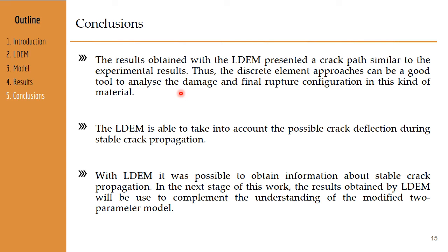Thus, a discrete element approach can be a good tool to analyze the damage and the rupture configuration in this kind of material. The LDEM is able to take into account the possible crack deflection during the stable crack propagation, and with the LDEM it was possible to obtain information about the stable crack propagation. In the next stage of this work, the results obtained by the LDEM will be used to complement the understanding of the modified two-parameter model.